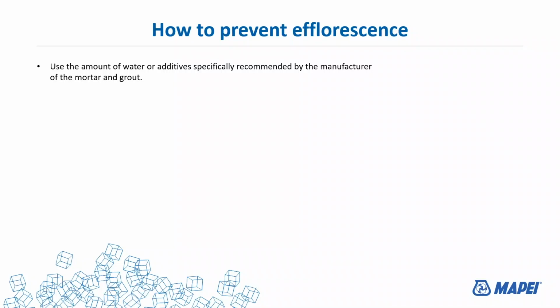We balance these products to be made in specific ways, and to mix it on the site, anything other than what's recommended by the manufacturer is a little bit out of the norm. So I would highly recommend that you follow the instructions from the manufacturer as to the measured amount going in. Keep the installation above the minimum temps recommended by the manufacturer on the bag. If it says can't be used under 40 degrees, I would say don't do it under 40 degrees.